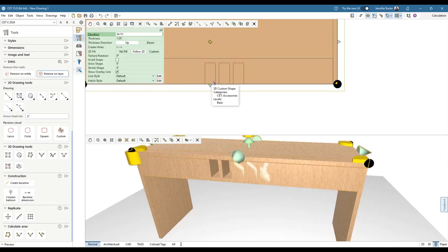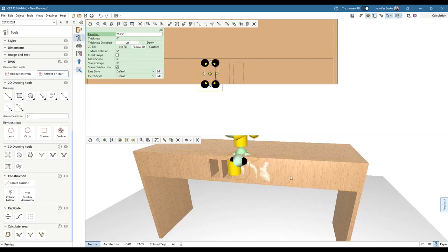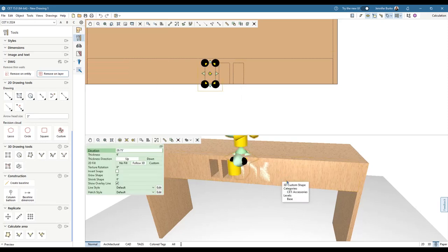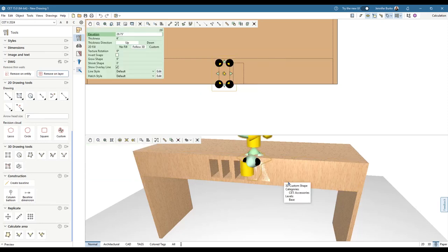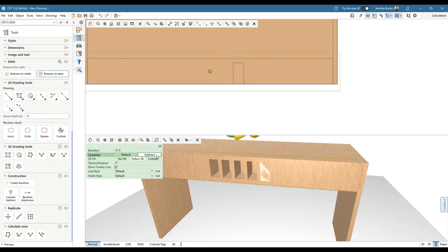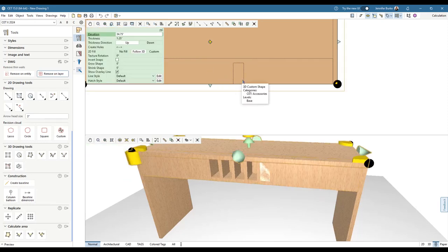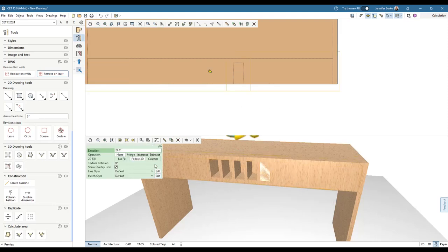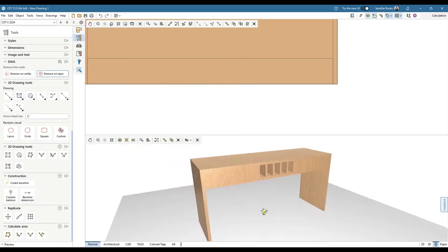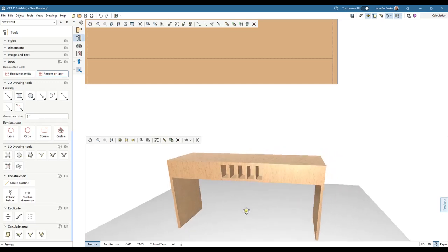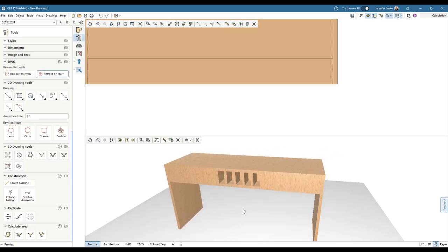So you're going to keep doing this. So we'll grab the smaller one, grab the outside, and click subtract. Small, bigger, subtract. We've got one more. And subtract. So we'll verify that all 5 holes are empty. We'll take a look. You can see the back of the laminate, the sides, and the top.